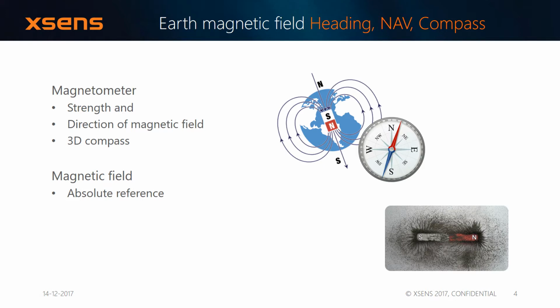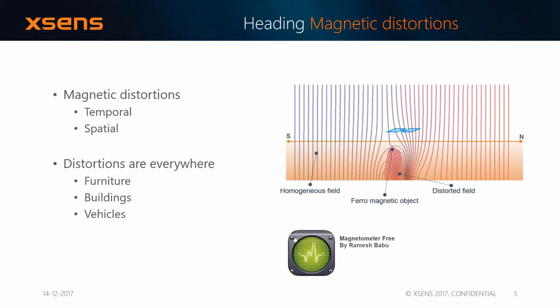What we use in these trackers are gyroscopes, magnetometers, and accelerometers. The magnetometers look towards Earth's magnetic field to get heading in the data that we want. The gyroscopes we use for orientation, and the accelerometer we use to determine the gravity of Earth. One of the downsides is that magnetometers tend to get distorted by magnetic disturbances.